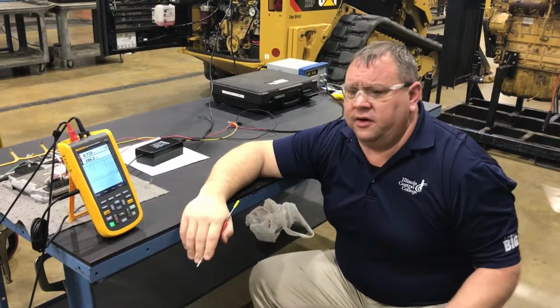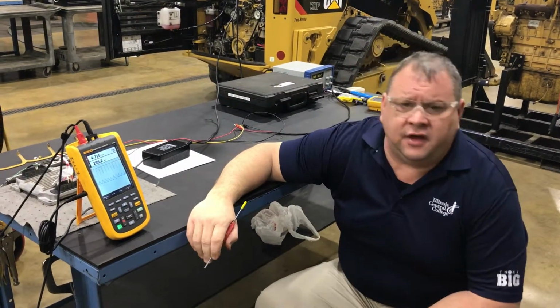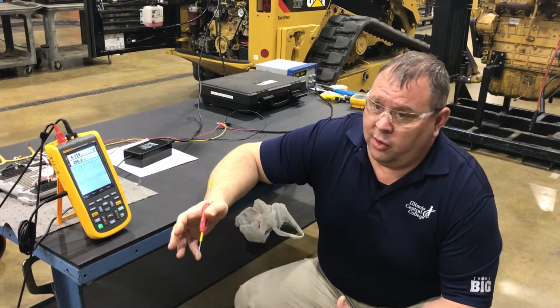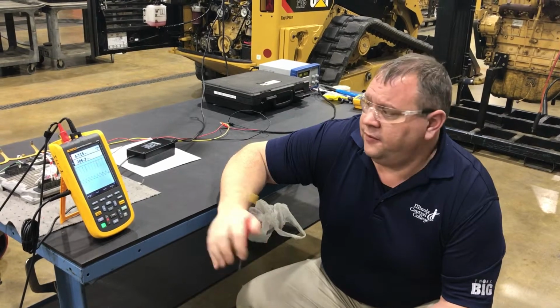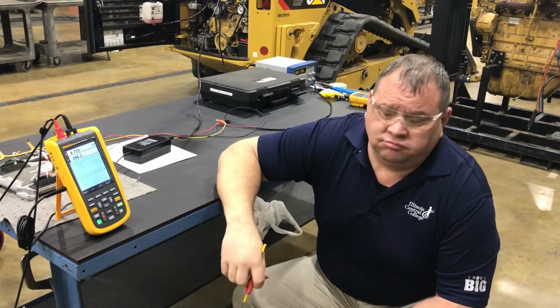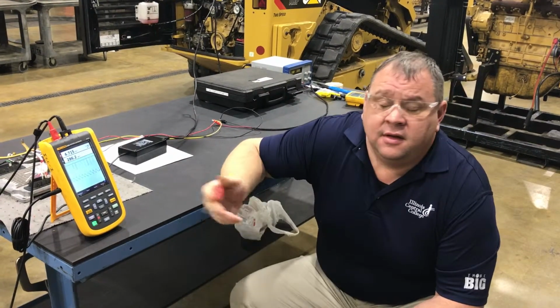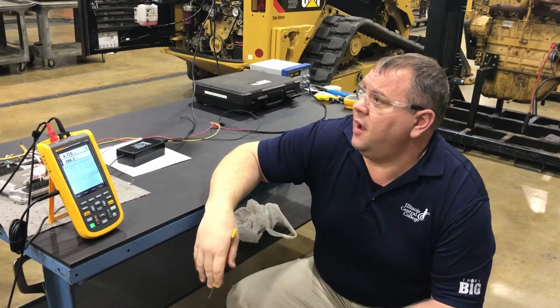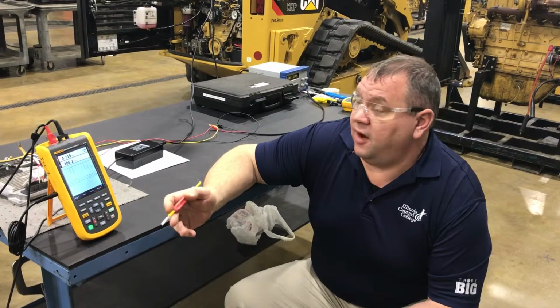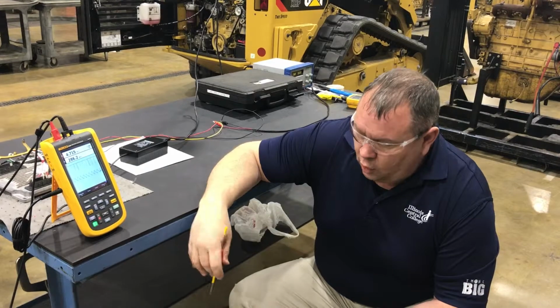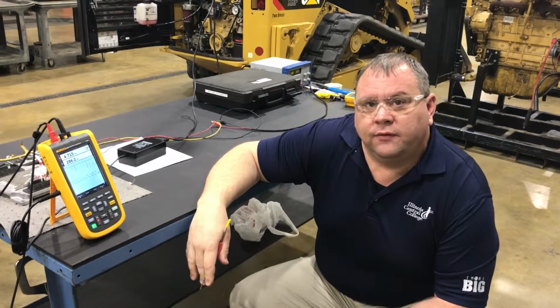If we do it on another engine, say we did a cylinder cutout test first and we had a weak cylinder number 5 on a 6-cylinder engine, but we don't know if it's mechanical or if it's the injector itself, I could just put the current probe on and crank it over. If I've got one that's dropped below the rest, then I know right there that I do have a weak cylinder mechanically. If I want to verify which one, then I need to jump on the cam sensor and determine which one is number 1 and then go through firing order from there.